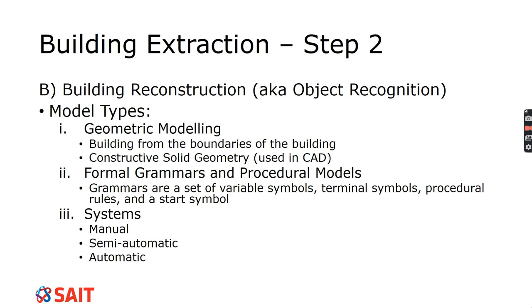If you did terrestrial, this is really where you're going to extract that. So combining Lidar with terrestrial laser scanning is really powerful, because you can get rooftops that you didn't have before. You're going to get that multiple return information with the Lidar. And then if you include the terrestrial laser scanning, you're going to have all of that detail. So it's really, really beneficial to do that. And we refer to this as object recognition.